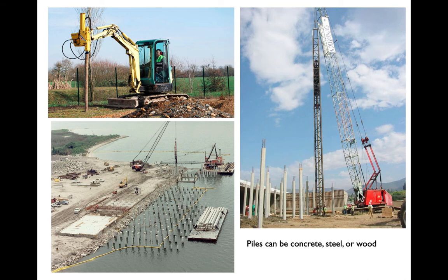Here's a similar case. This is a pile driver, and you can see that the science behind it is really simple. There's a giant weight that gets lifted up and dropped, and every time it drops, it pushes that pile further and further into the soil. Eventually, every time they drop the weight, the pile won't move, and that's when they say that it's hit its total refusal, is what they call it, and they can rely on it then to provide a fairly robust resistance to loading above. This is resisting a dynamic load. All we're asking it to do during its lifetime is resist a static load.